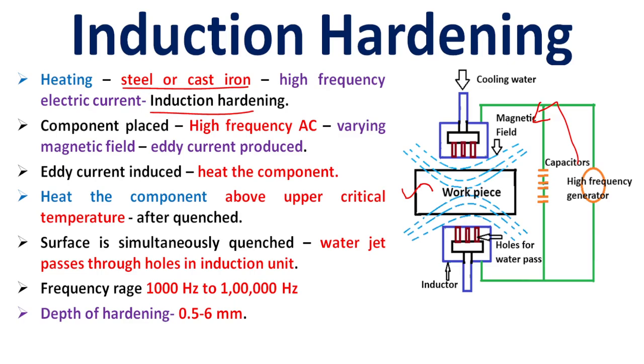That magnetic field produces eddy current, and this eddy current induces heat in the component, heating the workpiece and the material above the upper critical temperature.